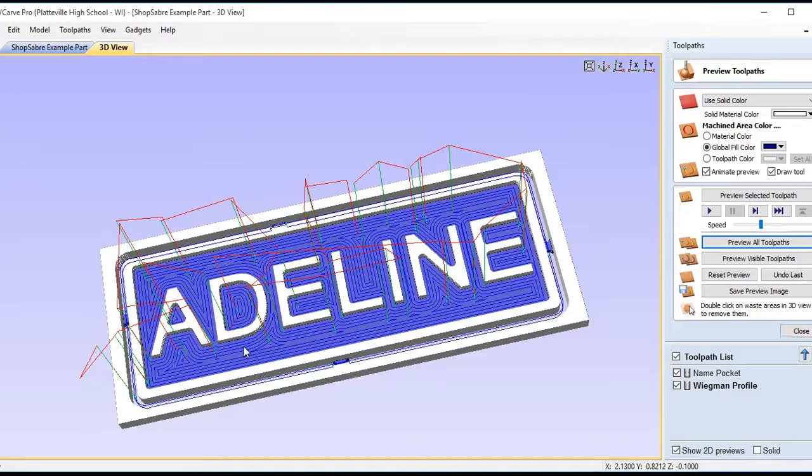Okay, obviously the first tool path that it's going to run is going to be carving or hollowing out around the letters in the sign, and the second tool path will be the profile, where it cuts our sign out from the larger piece of wood. Okay, so that will save us some time. But before we get to that, there's a couple things I would like to go back and edit. And the reason for that edit is simply because I want the signs to be a little bit thicker than what we originally made them.